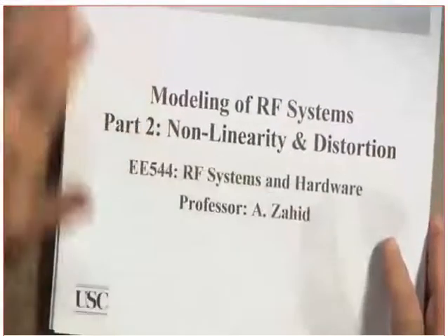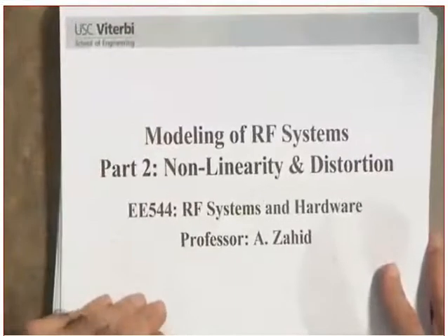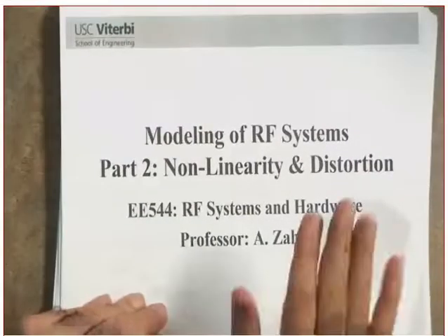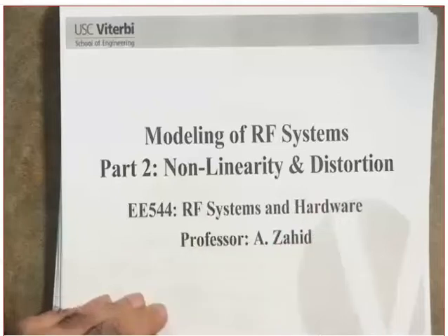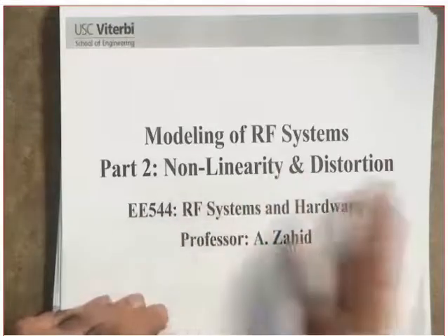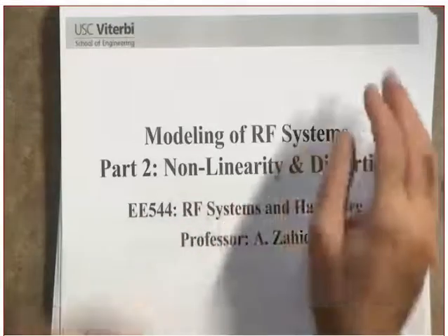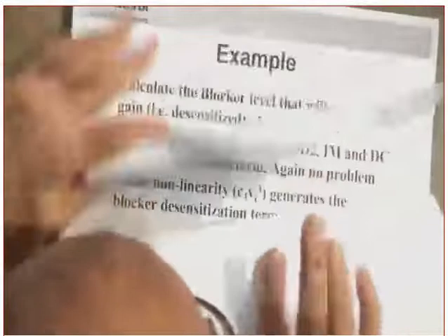Okay, so let's look at what? Let's look at the nonlinearity and the distortion. Clear? Always remember, the nonlinearity will what? Will determine what is the what? The highest received power possible, not the lowest. Are you following me or not? In other words, we are not talking about what? Sensitivity here. Let me show it to you so that you understand what I'm talking about.